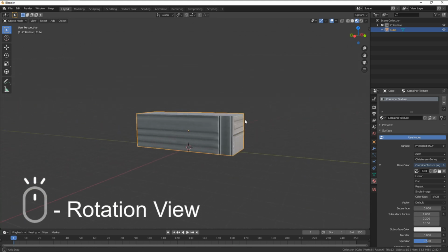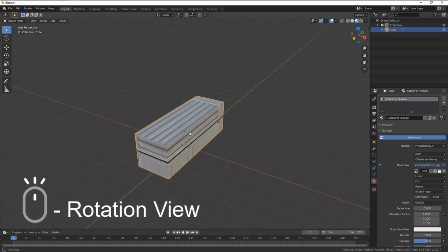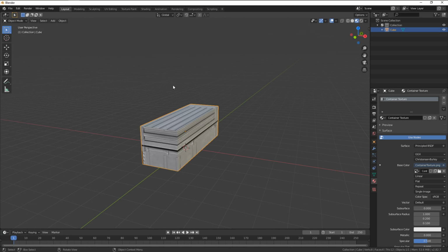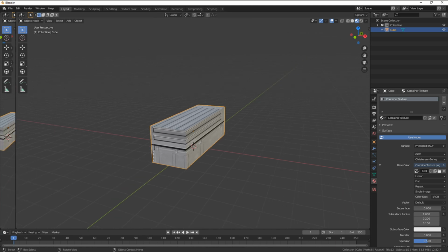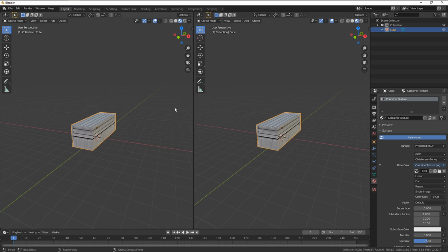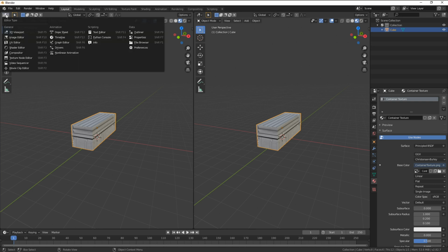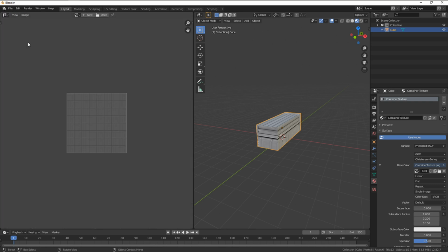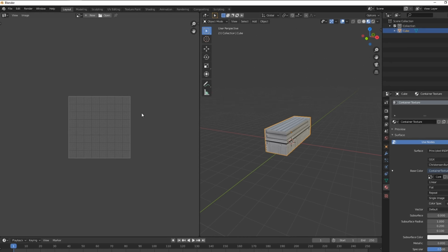Once added, you should get this weird layout. This is Blender taking a guess at the layout, and now we have to realign it. Create a new window by going left of the editor tab till a crosshair reveals itself, and drag it open until you have a 50-50 split. In this new window we want to view our material, so hit the editor type and change this to UV Editor. It may appear blank at first, waiting for us to activate the material.